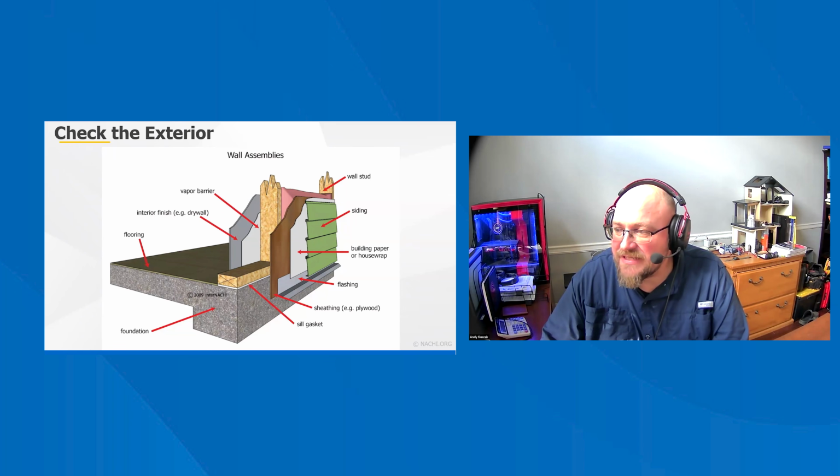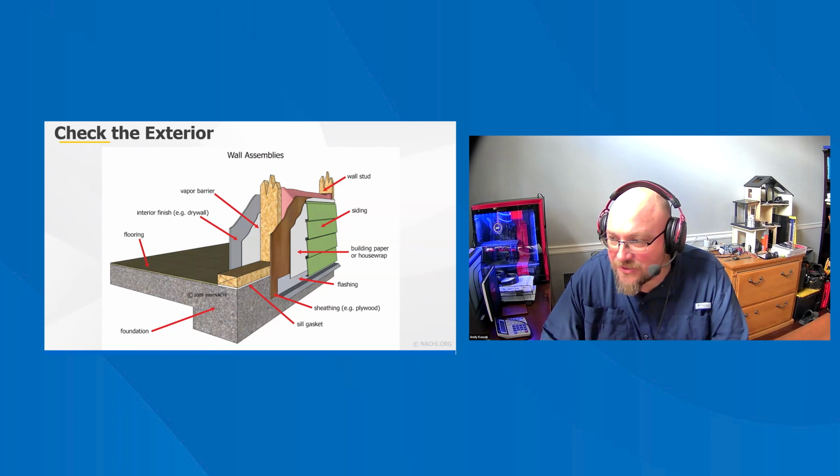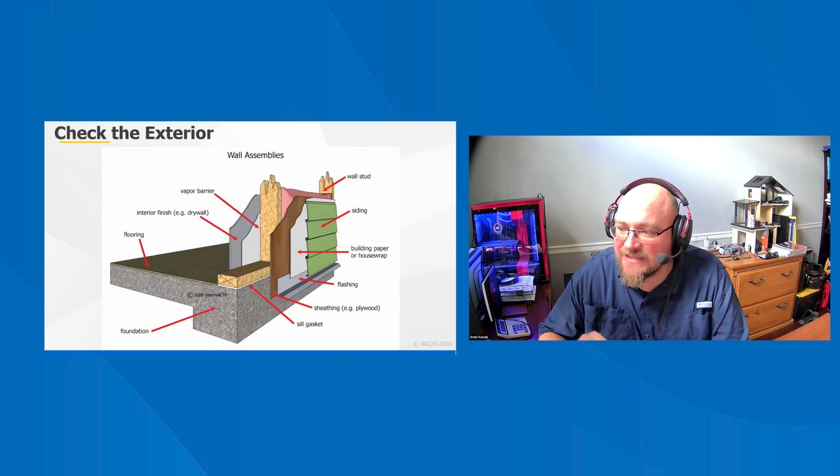The benefits of air sealing. Air sealing reduces heat flow from air movement or convection. Air sealing prevents water vapor in the air from entering the wall assembly. In a 100 square foot wall, 1 cup of water can diffuse through the drywall without a vapor diffusion retarder in a single year. 50 cups can enter through a half-inch round hole. Air sealing is 10 to 100 times as important as installing a vapor diffusion retarder.